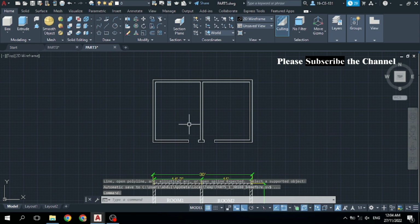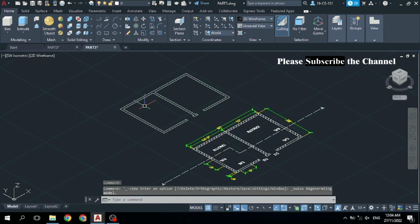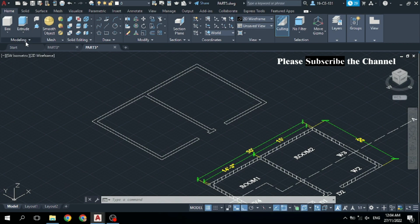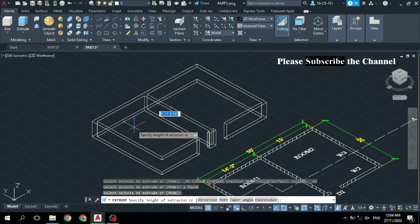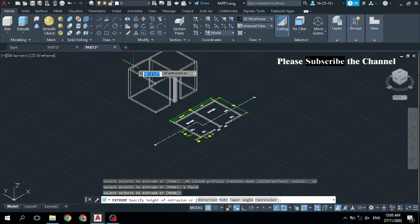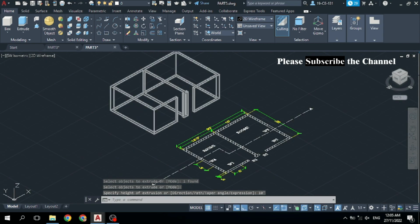And after that, come to this lift upward, click on this top and select isometric view. And after that, come to this extrude command, click on this extrude command and select these two room walls and press enter, and now go upward. These two rooms are the ground floor, so the height is 10 feet. So type 10 feet and press enter. Now you can see these walls having 10 feet height.